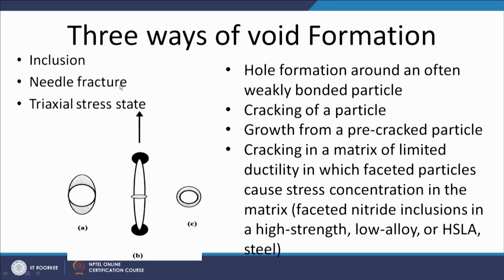But in the case of needle-shaped second phase particles, the voids are formed at the tip of the needles, where the stress concentration is high. When the triaxial stress state exists, the void will be formed all around the second phase particles. So, these are the different situations where such void formation takes place.